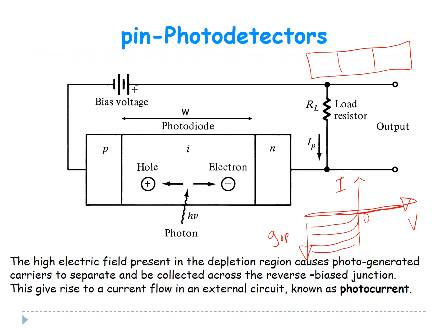Now, just like in the solar cells, the important region in your photodetector is this: if this is my P, this is my N, and this guy here is my W, the illumination should also be within LN on the P side and within LP on the N side.